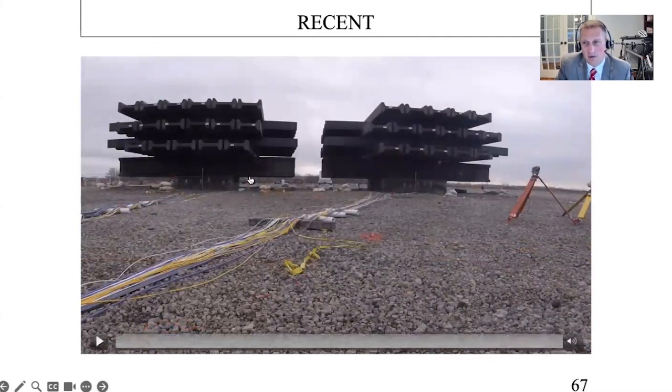So here are those two pile groups looking from a different viewing angle. Again, this is 1.5 million pounds of dead load that's placed on it. Those are the largest beam blanks they make, so each of those is 50,000 pounds on top of this. We have the pile group.